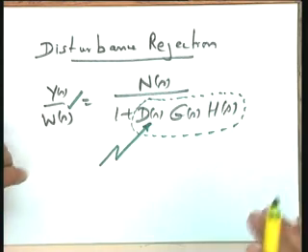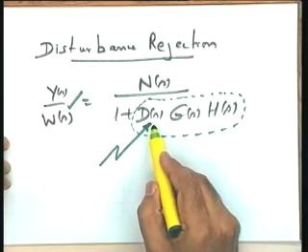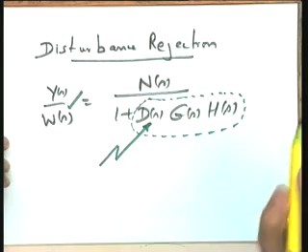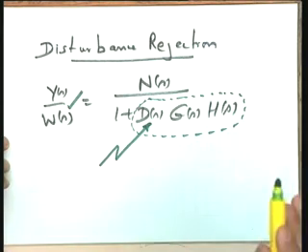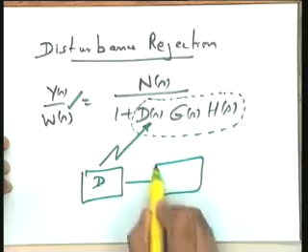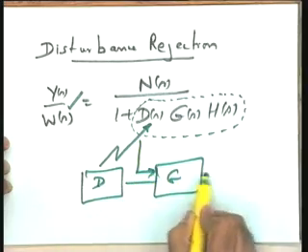Now because of the feedback action, D(s) is your controller, it has got the information about the effect of disturbance on the output. Since it has got information about the effect of the disturbance on the output, it can take appropriate action to reduce the effect of the disturbance. But as far as your open loop scheme is concerned, you just recall this scheme D and G. Let us say disturbance acts over here.